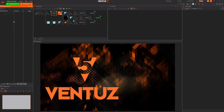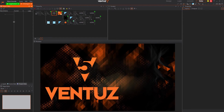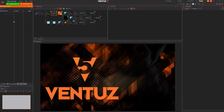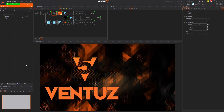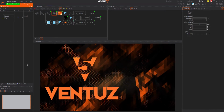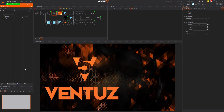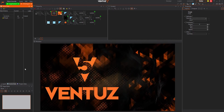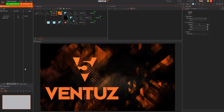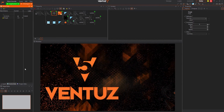The project data works similar to the scene data. The data channels here work for the whole project instead of only the scene. The main purpose of scene and project data is making certain properties in your project or single scenes accessible from outside. This way you can communicate with other programs from inside Ventuz or vice versa. The director is one example for an application that uses this technique. Since this does not regard the designer in general and is a very wide topic, it will not be covered in this series.